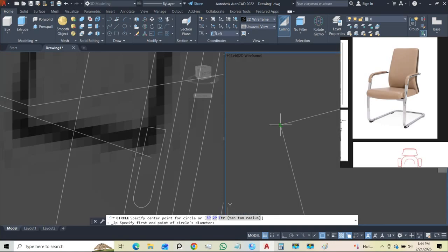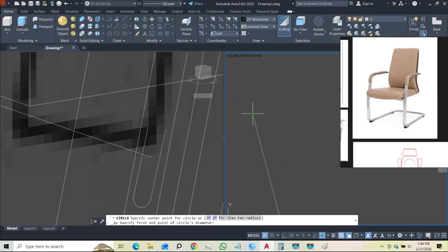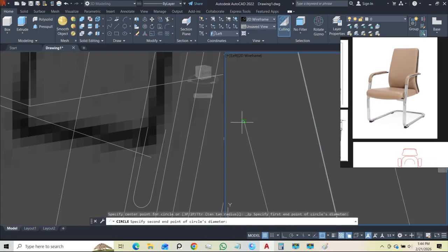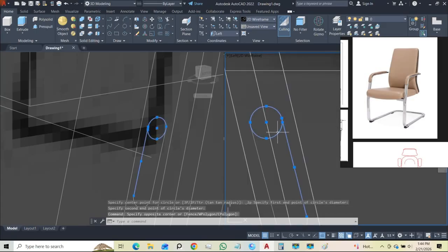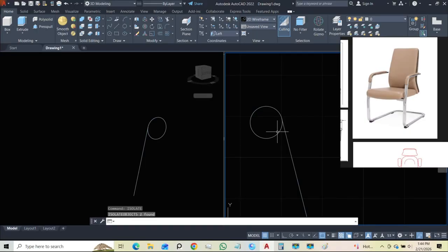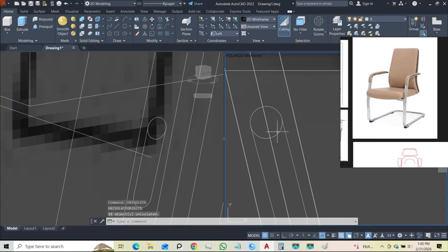2 points. So just click on the end. It's very important. Or first off, let's remove this. Click on 2 point circle. Should be able to snap to that end. Is end point that we want to snap to. Also end point, not perpendicular. So now if I select this, isolate, select this, this, and this.